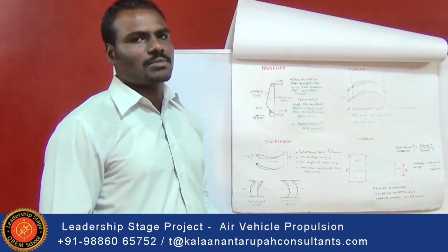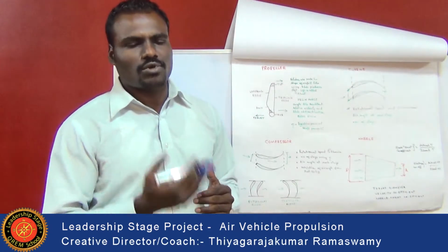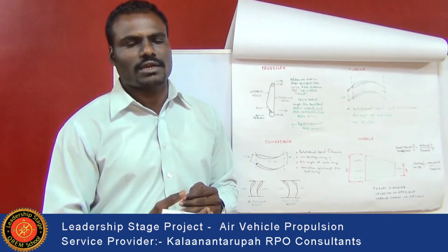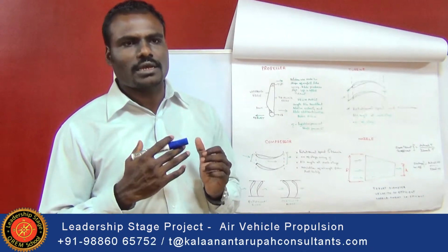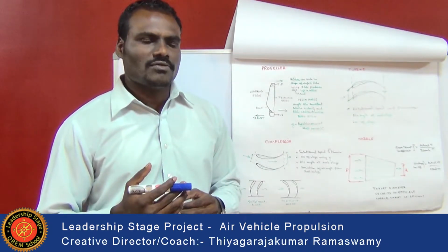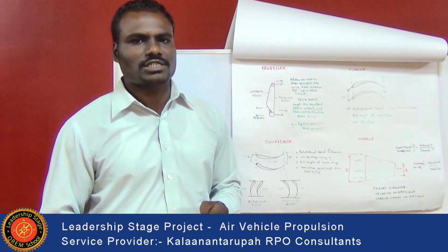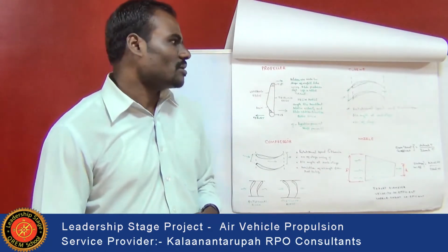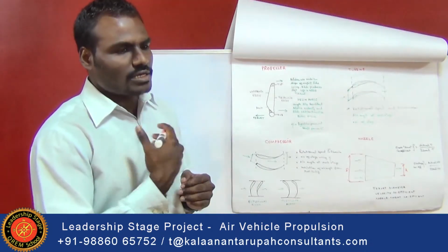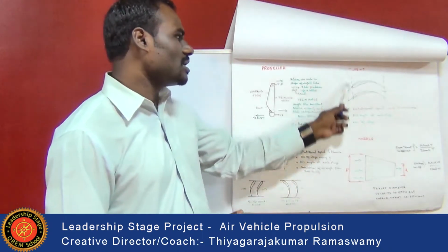Next is the combustion chamber, which is to be designed in order to maintain thermal protection, so that heat should not get dropped. In order to get better efficiency, it has to be made with a highly resistant material, and there should not be any temperature drop or pressure drop over the combustion chamber. After the combustion process is carried out, the exhaust coming out from the combustion chamber enters into the turbine.